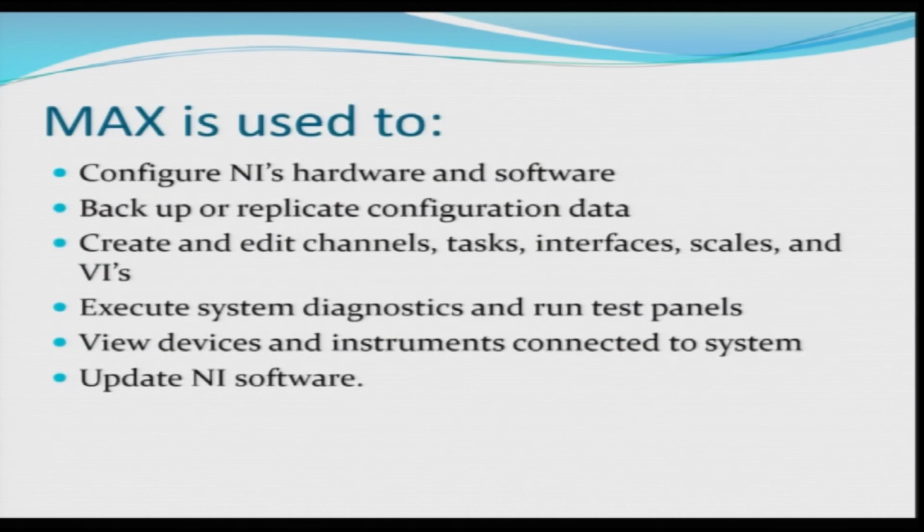MAX is used to configure the NI's hardware and software, backup or replicate configuration data, create and edit channels, tasks, interfaces, scales and VIs, execute system diagnostics and run test panels, view devices and instruments connected to the system, and update NI software if any.